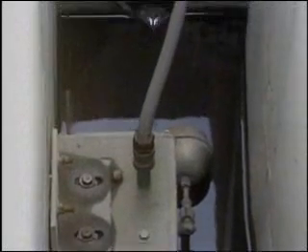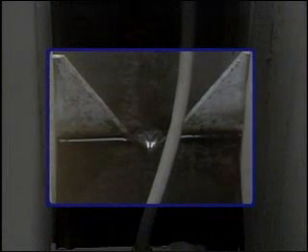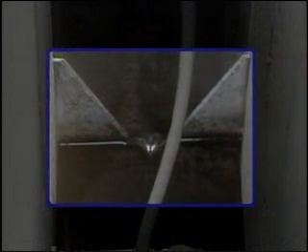Now, not all flow measurement devices are used to measure flow in enclosed passages like pipes. Some are used in open passages. These devices are often called open channel flow devices. One type of open channel flow device uses a weir. A weir is basically a dam with a notch at its top. In this arrangement, the level of the fluid behind the weir is used to determine flow rate indirectly.